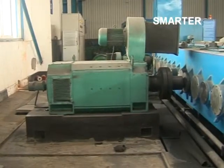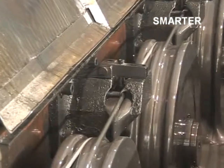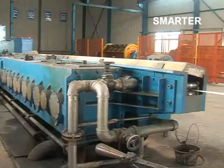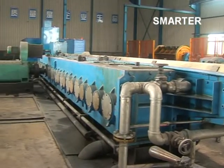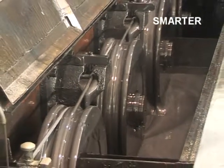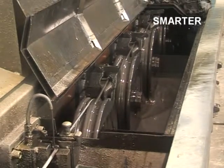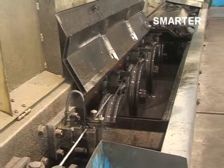The drawing machine consists of main motor, main machine, capstans, seat, cover, and final capstan, etc. Gears inside of the machine are ground and the rate of the speed depends on the elongation of aluminum. The diameter of the drawing capstan is 450mm, one-line structure. Surface of capstan is tempered and coated with tungsten, with high rotary speed and strong rigidity.